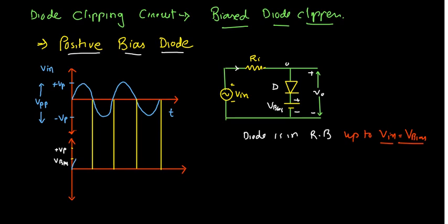This is the first condition. So you see what will be the output here, the diode is going to be reverse bias. So V input equals V output over there, till the diode is in reverse bias. So that circuit is open. So whatever input we are going to get, appears at the output side. So up to this, our diode is reverse bias.